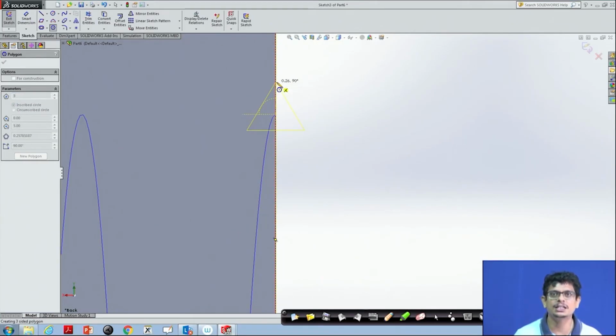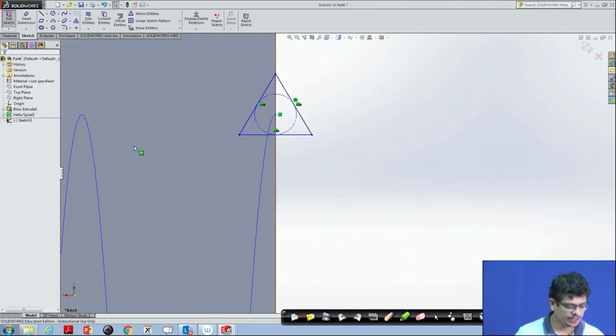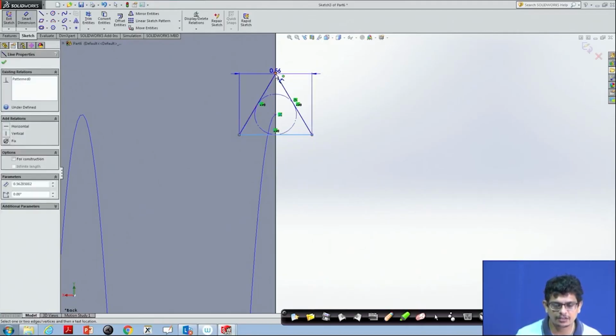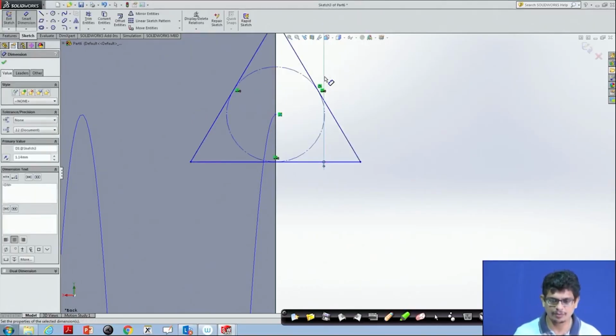Now, reverse this triangular tool cut, because now we want to remove the top portion. So, the triangle will be on top side and make it in that way. Now, this is supposed to be 1.1 mm. So, this height to that point is supposed to be 1.14 mm.